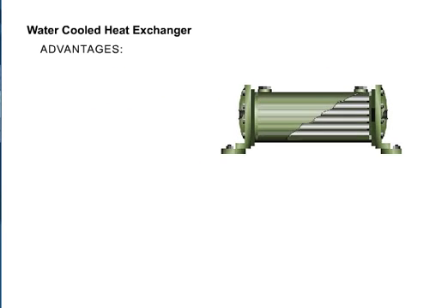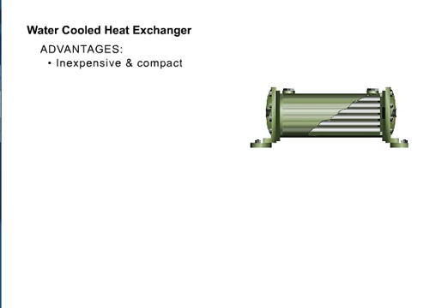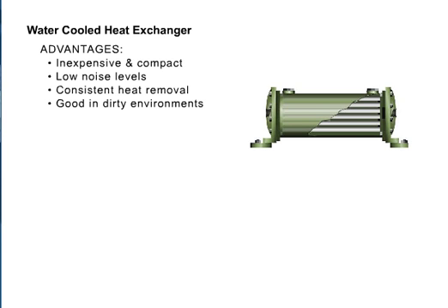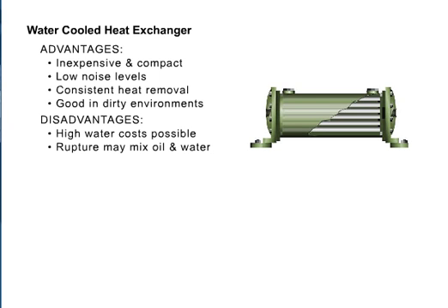There are advantages to this type of cooler. They are the least expensive, they are very compact, they do not make noise, they provide consistent heat removal year-round, and they are good in dirty environments. The disadvantages are, water costs can be expensive. With rupture, oil and water may mix, and they usually require regular maintenance from mineral buildup.